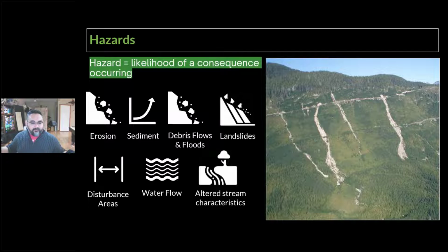So that's at the channel level. Sliding back to the landscape level, landslides are another hazard, and that's everything from as small as an undercut slope from a cut slope in a road, or the overloading of a slope below the road. But it also can be from just changes in the water regime, and so we're talking about stuff right from the landscape level down to just small levels like a rockfall or a slump.